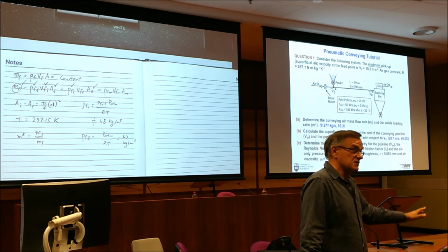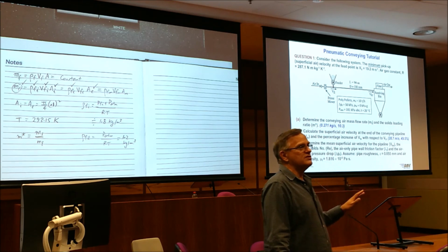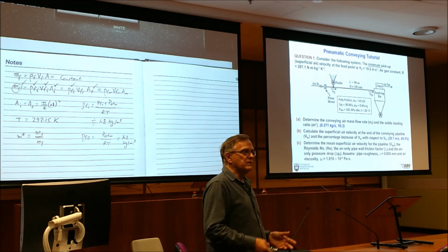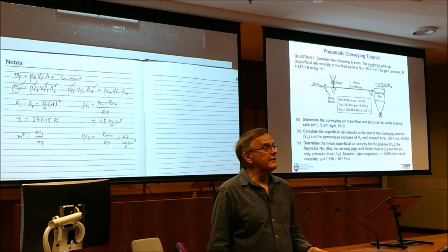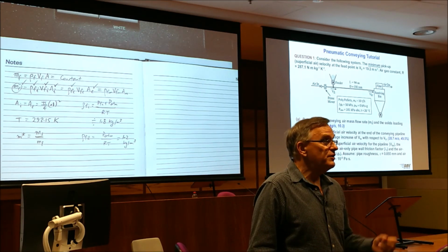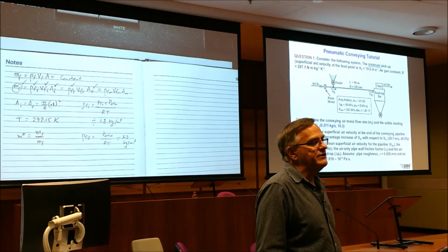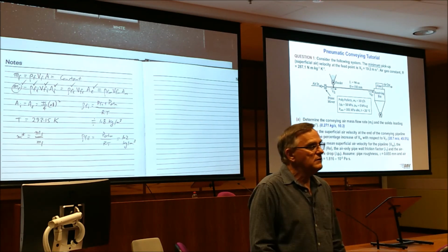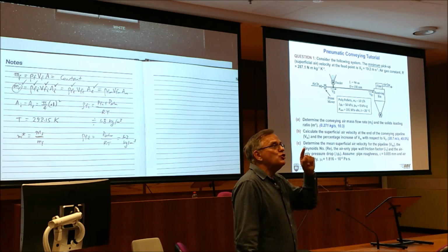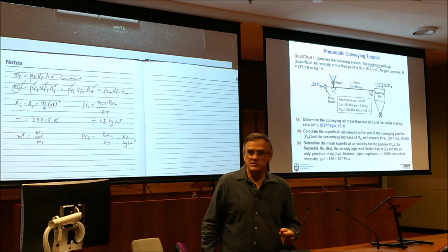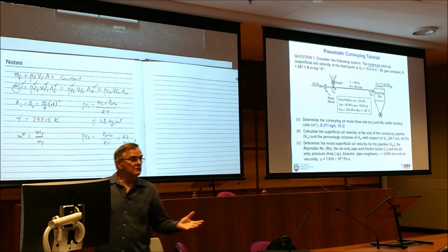This only affects compressible systems, gas systems, where the pressure difference is more than 10 kPa, because beyond that, things become non-linear. Below that, you can assume linear and you get away with it. Okay? But don't forget, use continuity. You can't go wrong, because you're obeying physics. Right? Any questions on that?